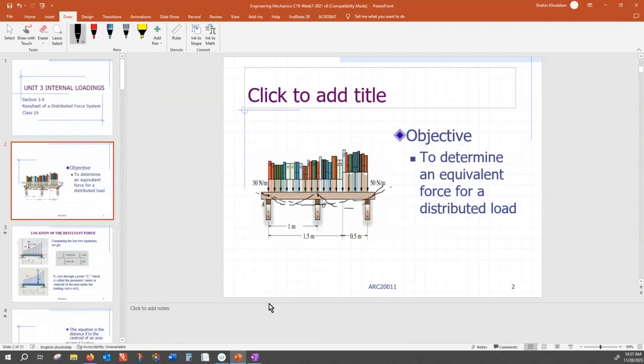And then every structure, when you see it, it's a big decision to make. The first big identification to start with is this: what kind of structure is it? If you can't classify it, the chances are you cannot solve it, right? A good example is a bookshelf. A good example is a bridge. A good example is an airplane wing. Imagine an airplane wing is a cantilever, but when the lift force is applied to it, it won't become longer or shorter. It changes the radius of curvature, right? So now you know what the beam is.